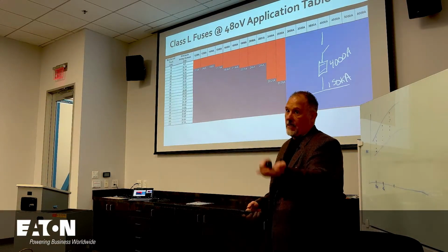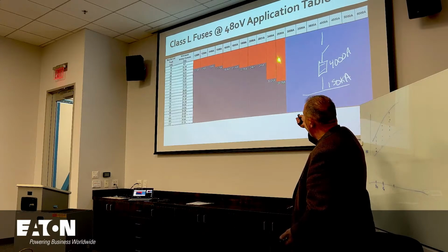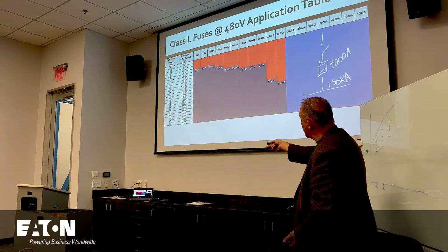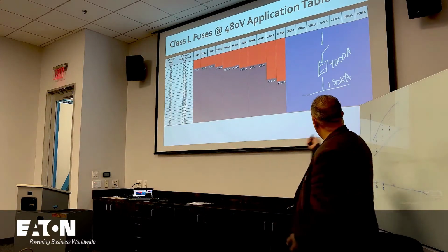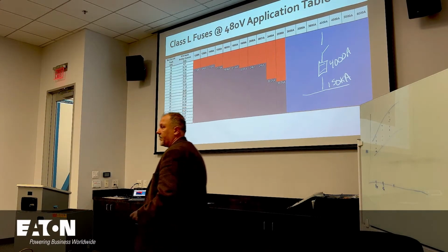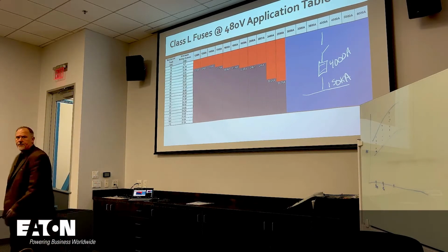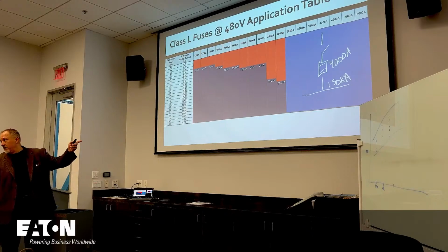So my suggestion is to calculate it at 106,000 amps and compare your arcing current of 37,006 with the instantaneous or the clearing time of the fuse, and determine whether or not it's 0.1 seconds, which is the requirement in the code. 0.01 second, 0.1.